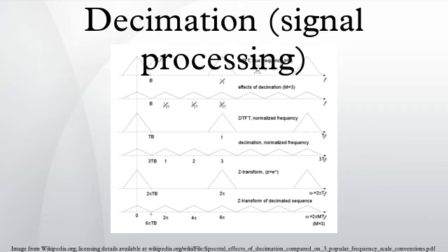The abscissa of the top pair of graphs represents the discrete-time Fourier transform, which is a Fourier series representation of a periodic summation of X(f). When T is units of seconds, f has units of hertz. Replacing T with MT in the formulas above gives the DTFT of the decimated sequence, x[nM]. The periodic summation has been reduced in amplitude and periodicity by a factor of M, as depicted in the second graph of Fig. 1. Aliasing occurs when adjacent copies of X(f) overlap. The purpose of the anti-aliasing filter is to ensure that the reduced periodicity does not create overlap.